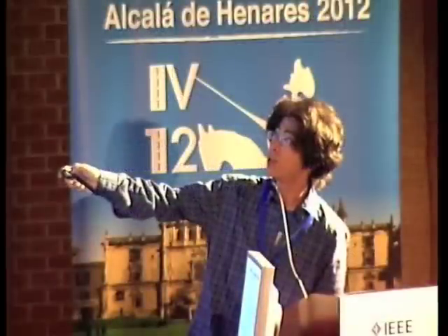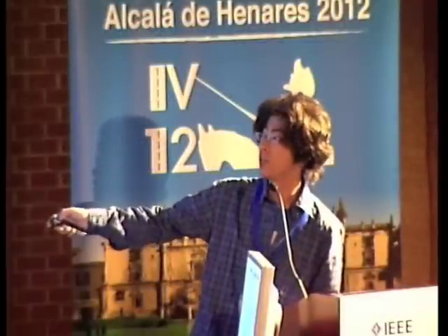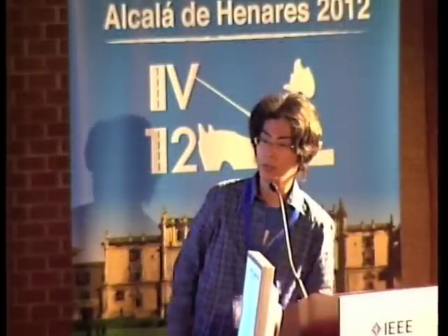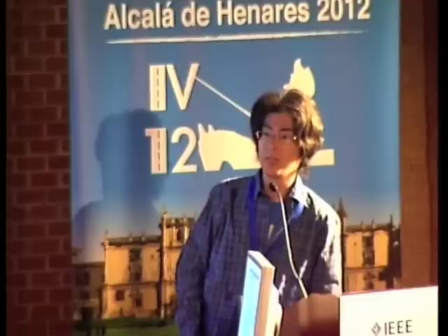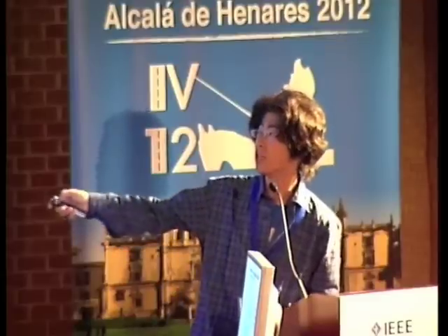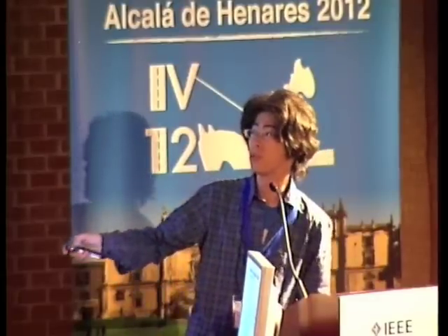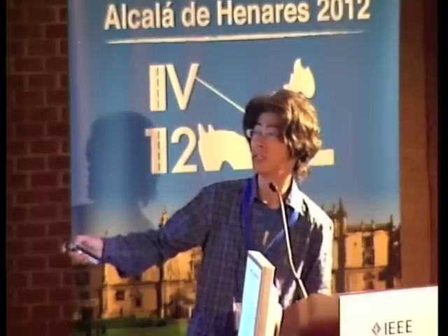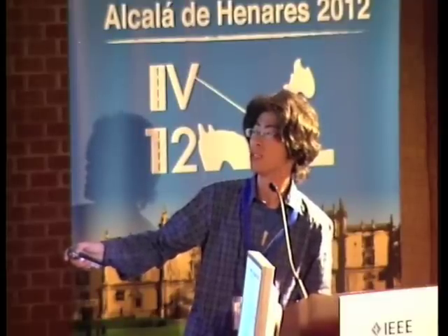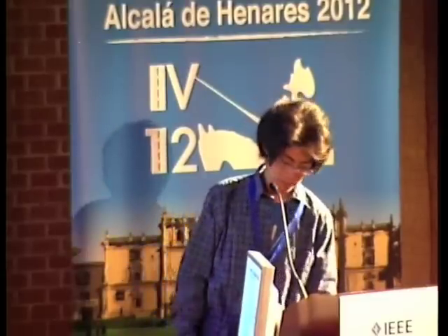Another point is the RFID receiver antennas. We use multiple antennas and they are placed on the vehicle. For example, it is placed on each corner of the vehicle, like this one, this one, this one, this one. And of course, we also use a gyro and acceleration sensor, sometimes called a 6-dimensional gyro sensor.